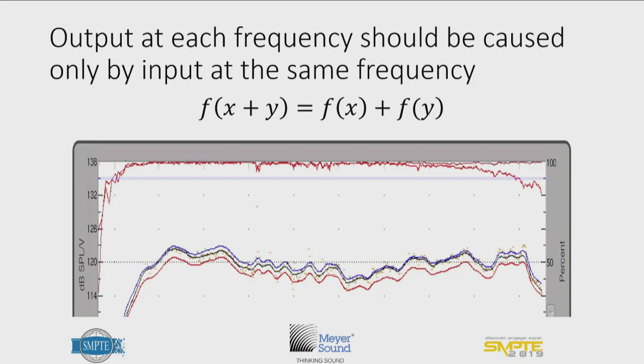So here's a measurement of a speaker which is exhibiting some compression. So you can see the black curve there is in between the blue and the red curve, but this speaker could still get louder. So you could increase the input of the speaker and the output of the speaker would still get louder. However, you have already seen a significant reduction in the coherence. So there is some clipping, distortion, or some other artifact going on.